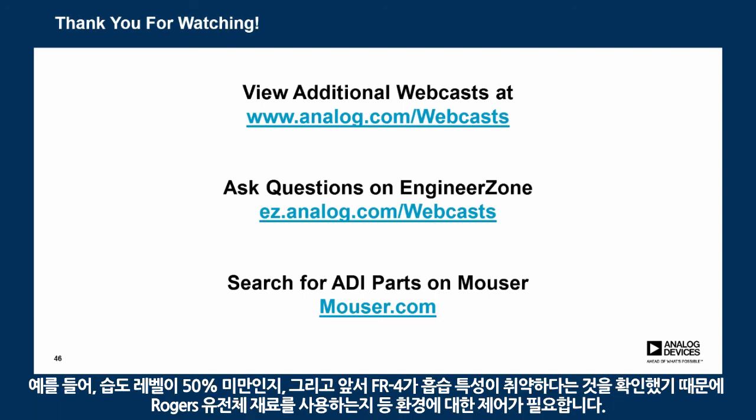For example, you can use it in a controlled environment, making sure that the humidity level is less than, say, 50%. Or use Rogers dielectric material, because conventional glass epoxy FR4 has poor humidity absorption properties.